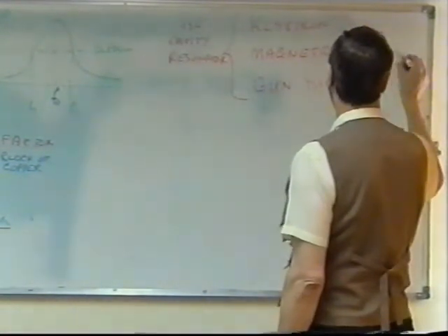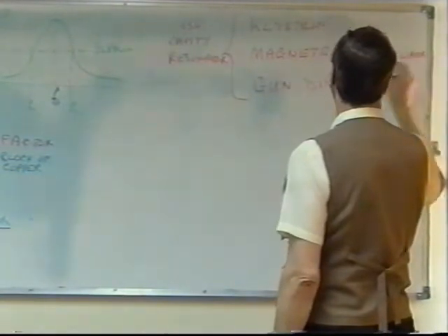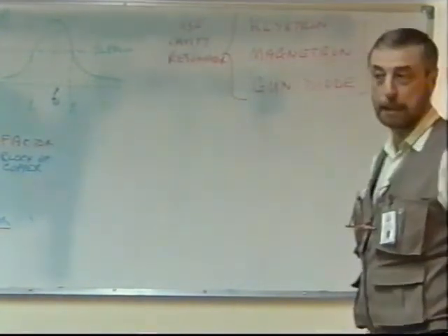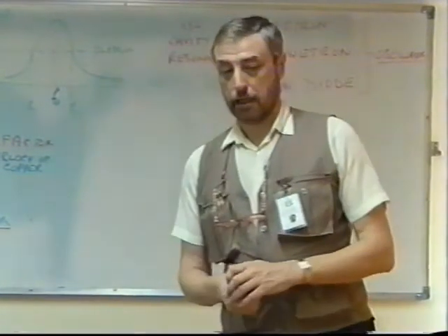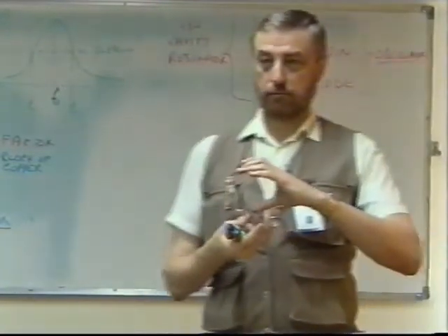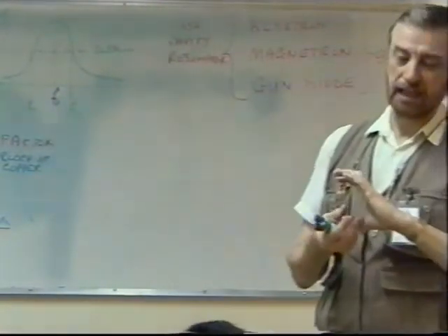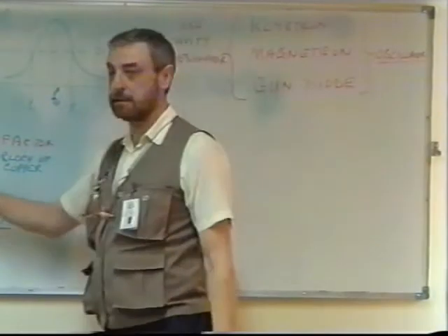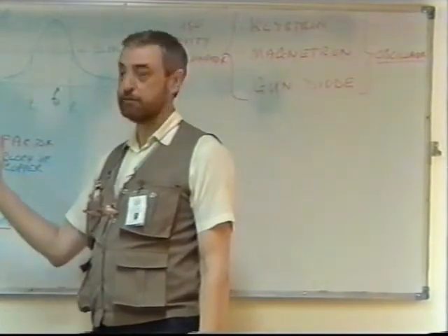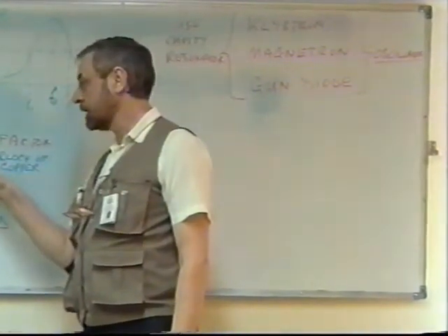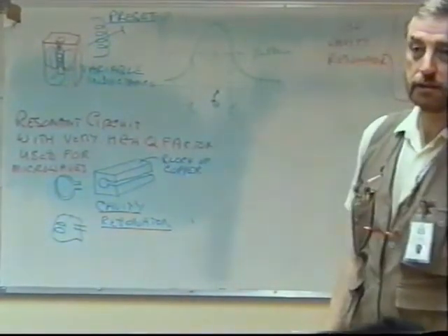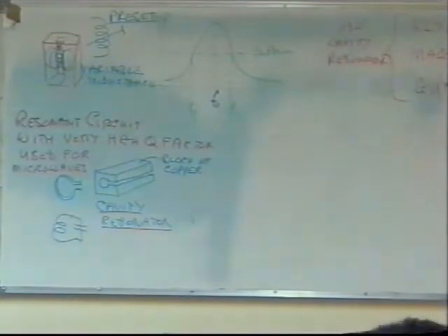How do you wire this? Well, for instance, in these two devices, the klystron and magnetron, it's built into a tube. Actually, it's not glass, it's metal, evacuated, and there's an electron beam that runs past these cavities. The electron beam oscillates between the two ends of the cavity at the frequency of oscillation to maintain oscillation. It's all done within an evacuated compartment in both these devices.